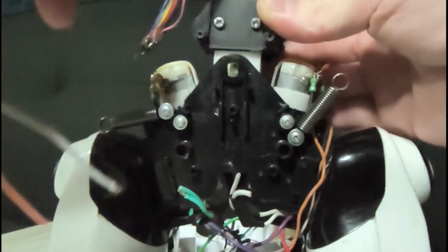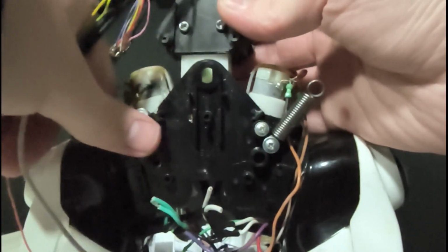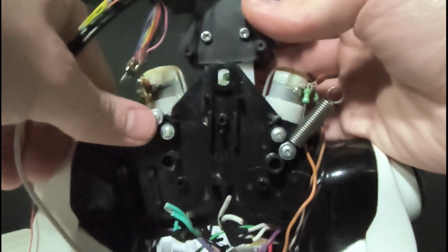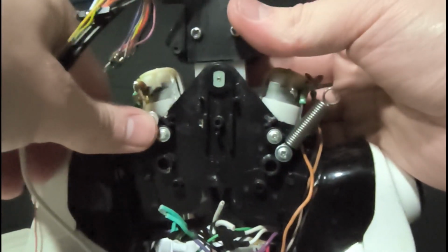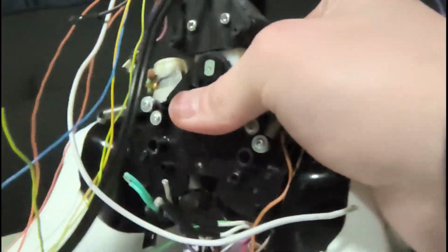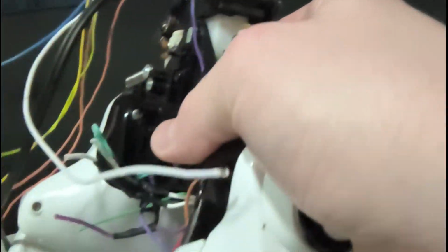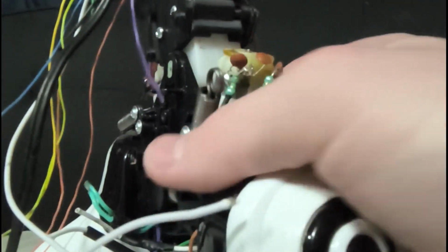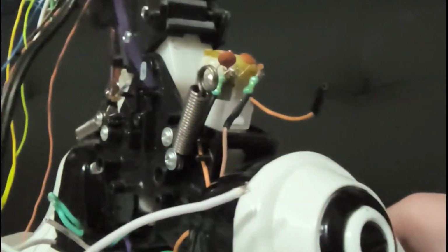And if we look at how the robot attaches to those feet, you'll see there's button lines, and then there's a 7.4 volt line coming from the batteries that's tied together, and then there's the speaker lines. You can have stereo or mono. The only difference is the wires will join together if you're using mono audio.